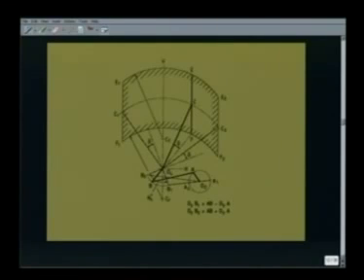Corresponding to B2, I draw this line O4C2 at an angle delta, which was 16 degrees, and corresponding to B1 again I draw at an angle delta 16 degrees to get C1. So O4C2 and O4C1 are the two extreme positions of the link 4.